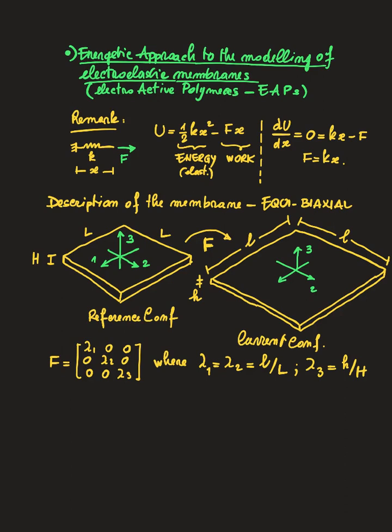Silicon, or similar materials used for these applications, EAPs, are essentially incompressible, and if they are incompressible, then clearly the determinant of F must be equal to 1.